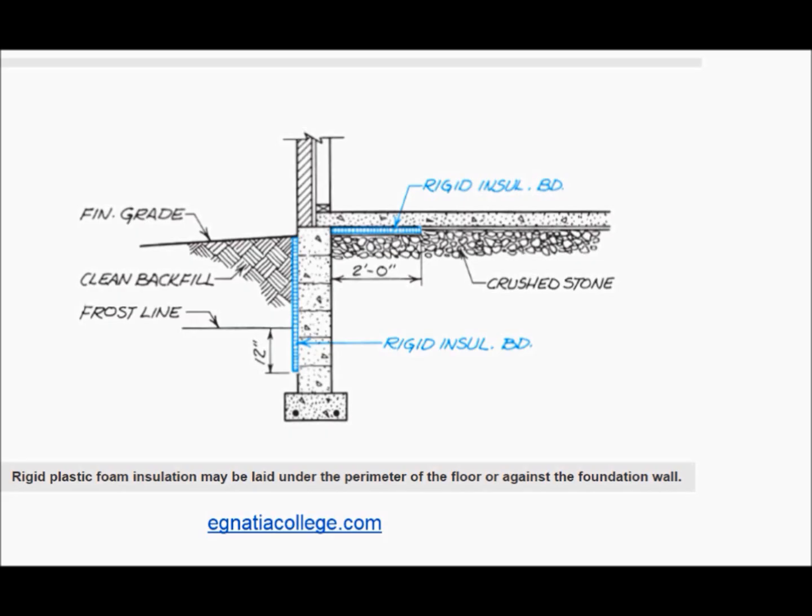To retard the flow of moisture from the earth through the concrete slab floor, the drawings may call for a layer of gravel over the entire area before the concrete is placed. A polyethylene vapor barrier is laid over the gravel under fill. The thickness of polyethylene sheeting is measured in mils. Insulation.